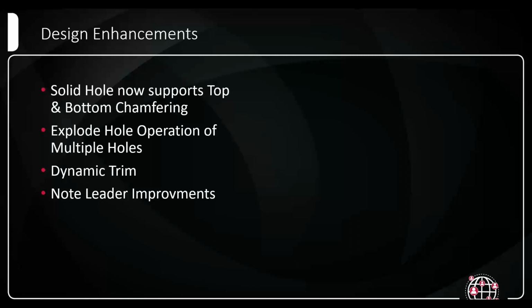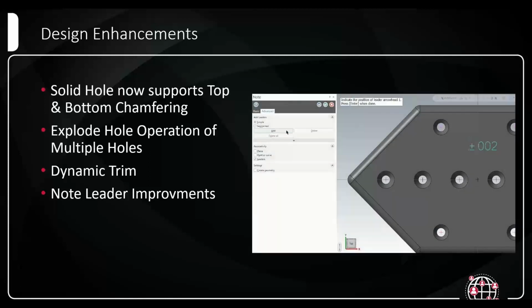Okay. Another thing that we've been kind of enhancing over the last couple of years is the note text and the design or the drafting text. You guys may have run into this when you try to make a note and try to give leaders to that note. In 2023, when you hit add, you can add a single note or leader at a time, but then you had to go back and click add again for a second one, click add again for a third, click add again for a fourth, and so on.